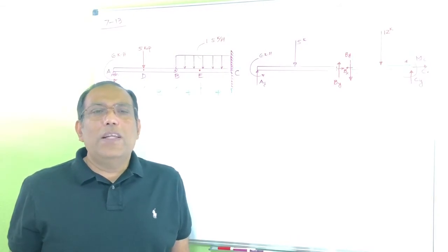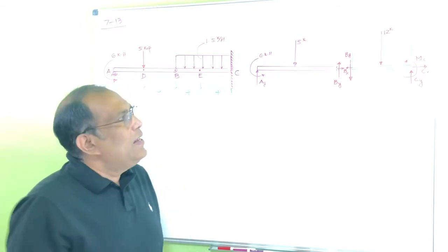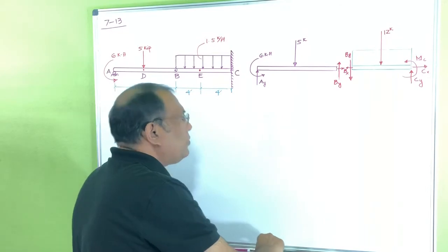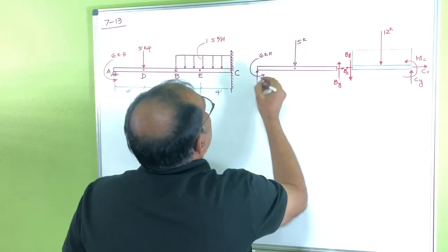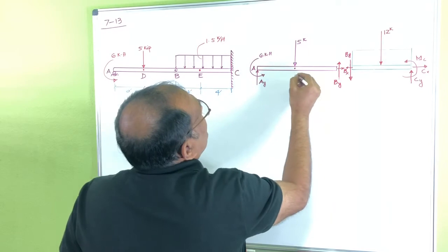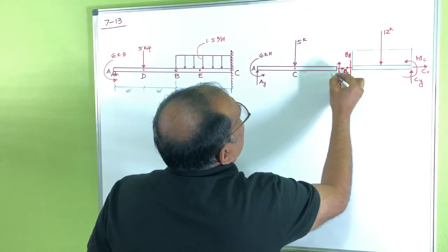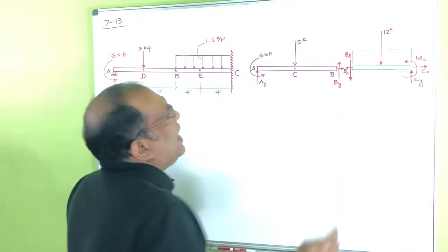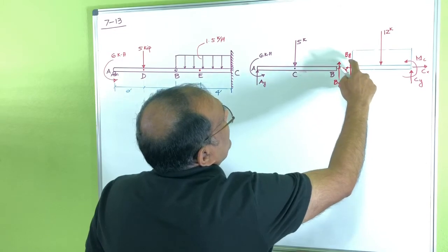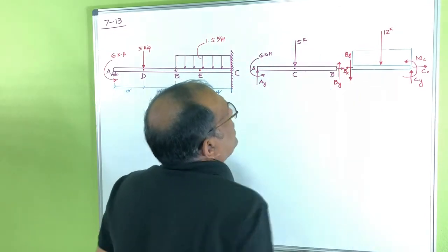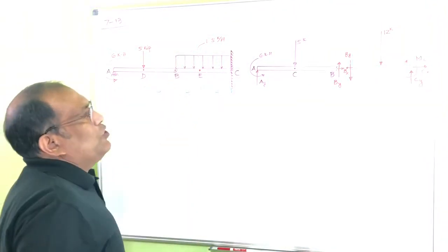So what you can do is open that hinge and show it with 2 force reactions. That's what I did here. You can see this is your point A, this is B, this is C, and this is point B here. I just assume this one is my Bx, this is By. Since I opened that one, the other side is in the opposite direction, downward and this way, so that when you mix them together, you don't see any force here.